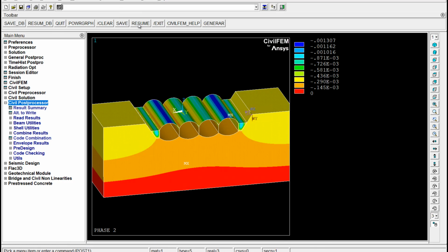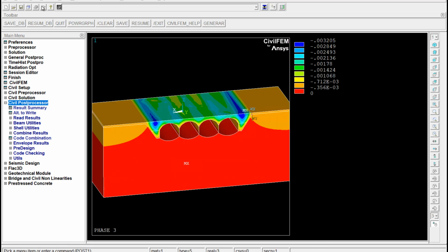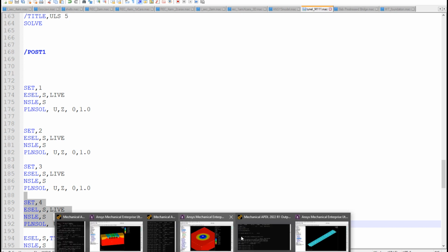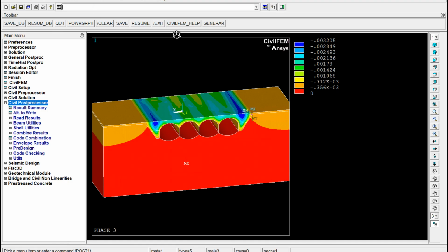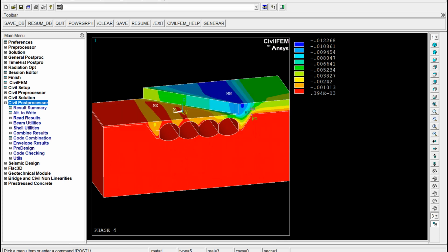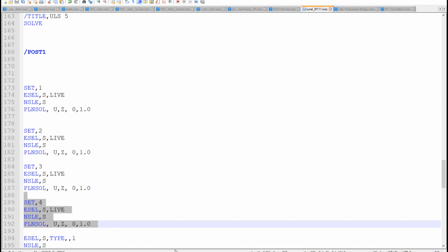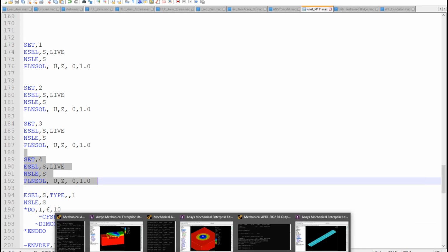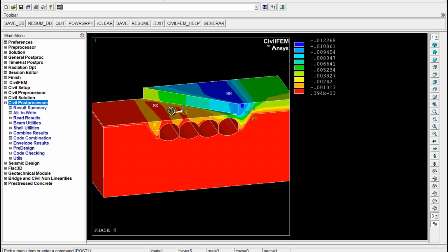This part is the first cuttings. Where this is filled. And the last part, the structure for the airport. And then the cover. And the last stage is adding some overloads on that part. So the model is exactly the same, but with some overloads. In this case, what we have done is performing the concrete design, considering every one of these load steps.